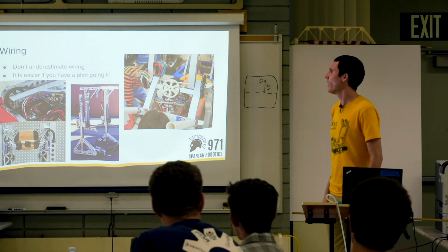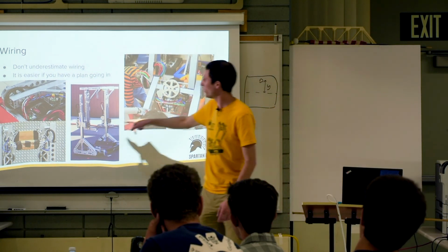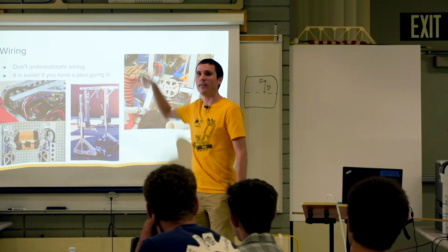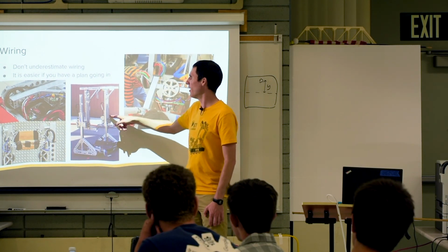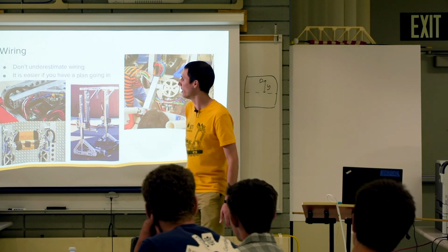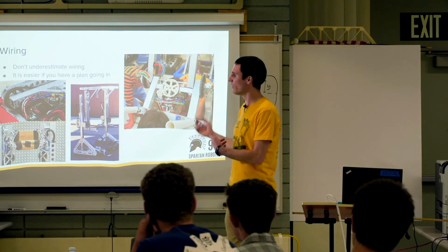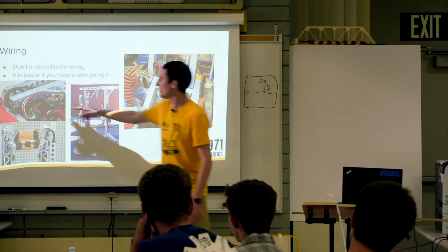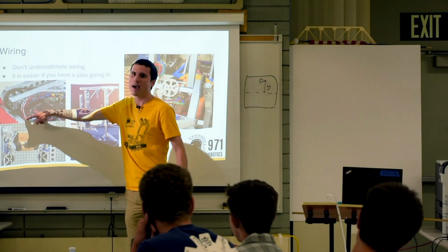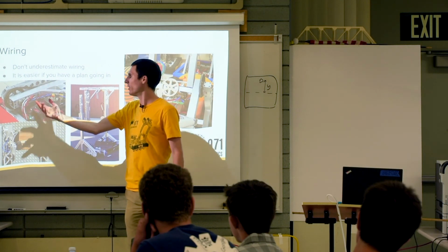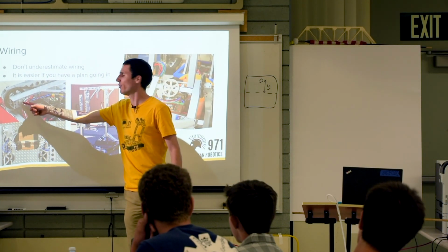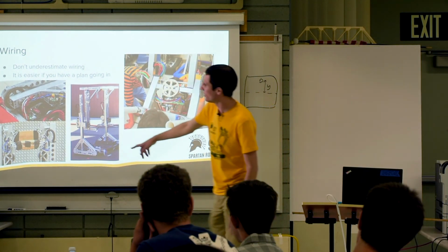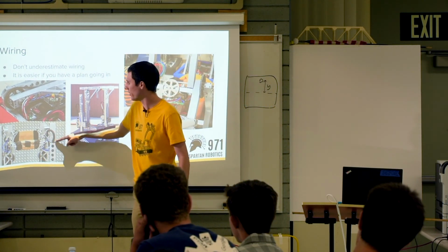If you notice, from our 2014 to our 2015 robot, we put an IGUS chain to manage our wire on the elevator. That helped us a lot, and we've since thought a little bit more about it. One of the tricks is in our 2016, we just run the wires next to the pivot. That lets you move the arm up and down, and the wires kind of float there. You can see the same thing here. We had space for the wire to go there.